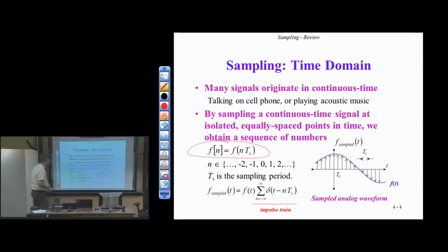All right, so the f of t here is being sampled at equally spaced points in time. So a little n of 0 corresponds to the origin. This is little n of 1. And I just keep taking amplitude values at integer multiples of the sampling time. So one way to look at what I've done is I simply have a discrete time signal, little f of n, and I simply have the amplitude values and nothing more.